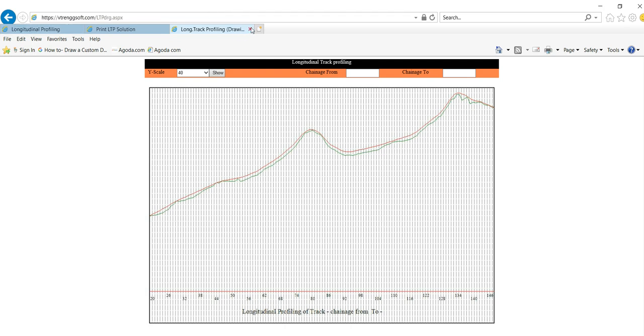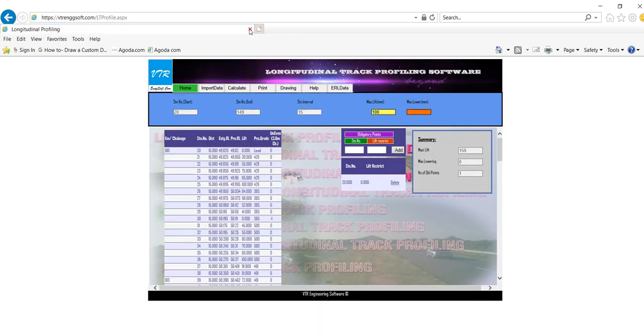So then we can close this application. Now at station 110, your lift restriction is 0. After entering, you have to add. So just come here. Now, one option, an obligatory one, is the beginning station. Normally at the beginning we don't lift, so the beginning station is 0. Now, we want to restrict the lift at station number 110. So click the add button.